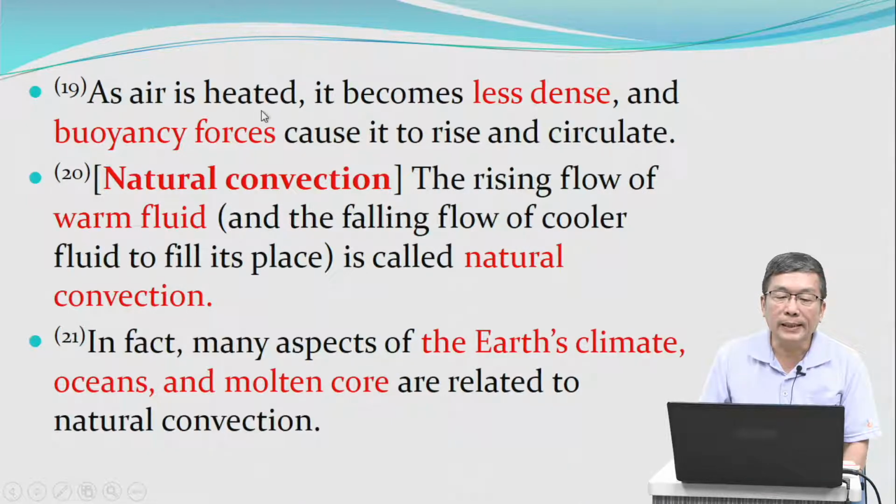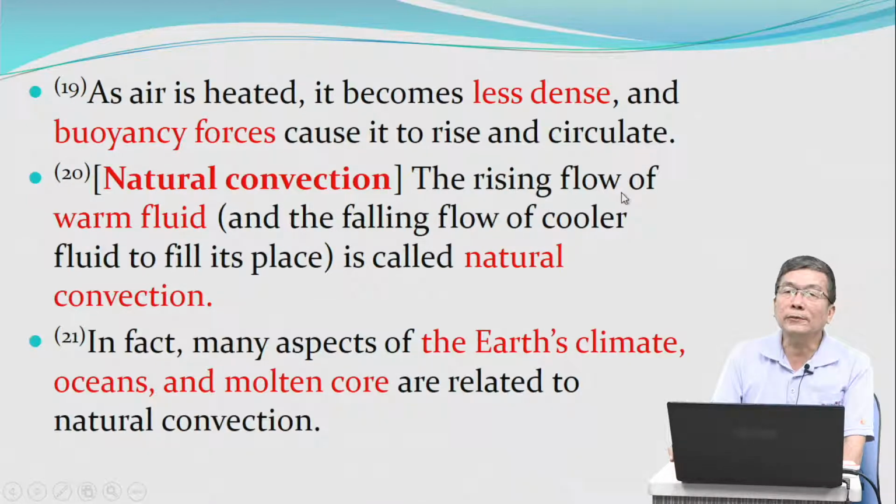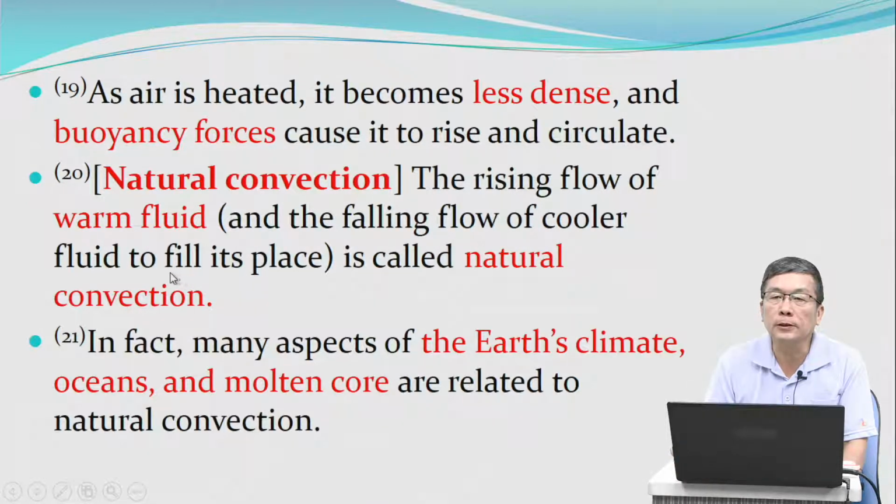As air is heated, it becomes less dense, and the buoyancy force causes it to rise and circulate. Natural convection. The rising flow of warm fluid and the falling flow of cooler fluid to fill its place is called natural convection. In fact, many aspects of the Earth's climate, oceans, and molten core are related to natural convection.